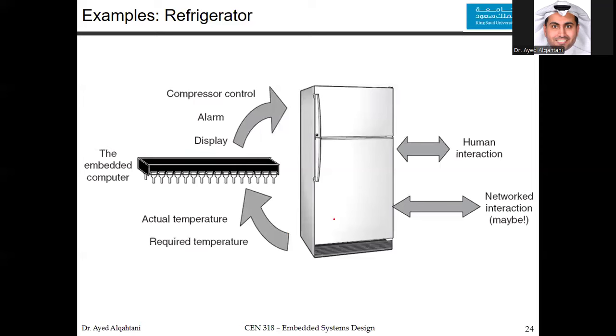Let's look at it here. You can see the machine clock in this example, to be able to draw it clearly. The FOSC is equal only to 4, meaning that the TOSC is going to be 1 over 4, which is 0.25. So for each clock, you have 0.25 seconds. Within a full second, from here, 1, 2, 3, and 4 to here, you have 4 clocks, or you repeated this clock 4 times within 1 second. And this is why the frequency is equal to 4. Each one of these clocks is 0.25 seconds.